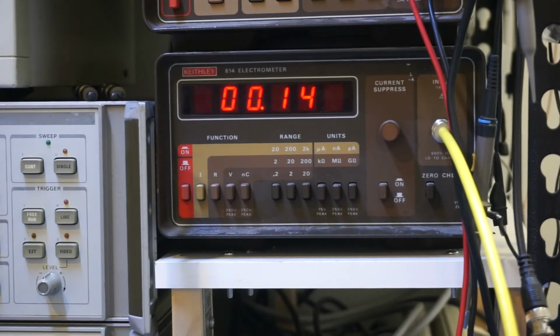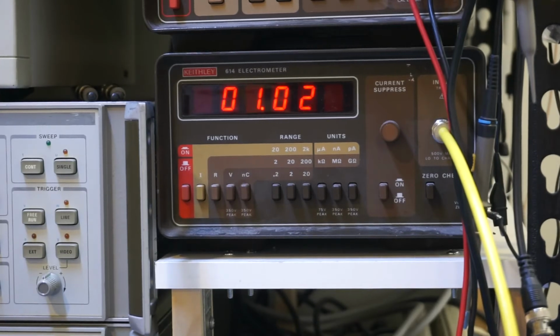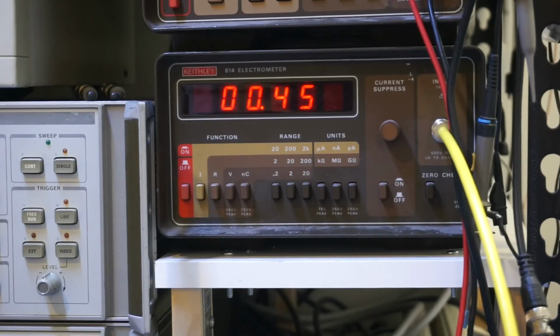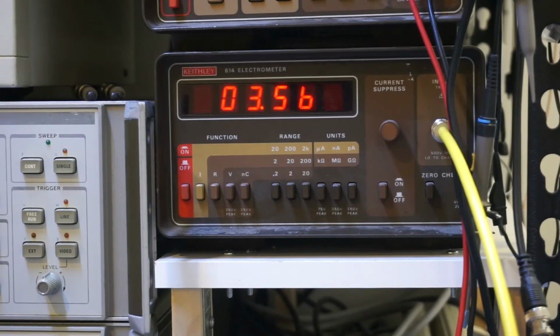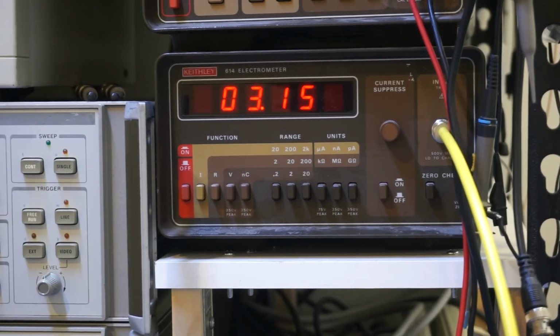Now I'm going to walk to the other side of the table and adjust the voltage standard, and then we'll get a reading for each voltage point. So I'm going to read out the voltage I'm setting, and we will do the current measurement here. Okay, so now let it settle again. So I'm going to change the voltage to 0.1 millivolt. And as you can see, I put it to 0.1, it immediately jumped to somewhere in a range of 3. So let's call it 3, because right now, when the resolution is high, it really jumps quite a bit.